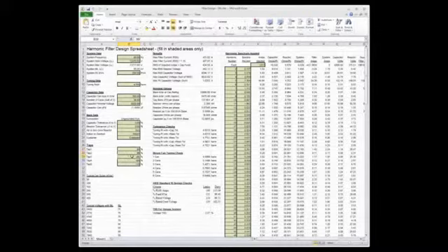Looking at the reactor taps, you see there are reactor taps specified here, and I have tolerance checks here. So I spec'd capacitor and reactor tolerance of 3%, 3%, and then you can see how the tuning point changes based on tolerance differences. Okay?